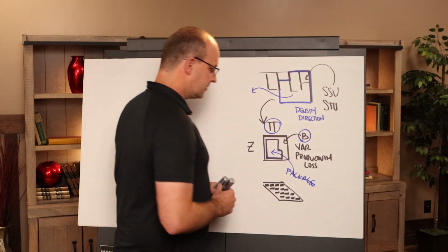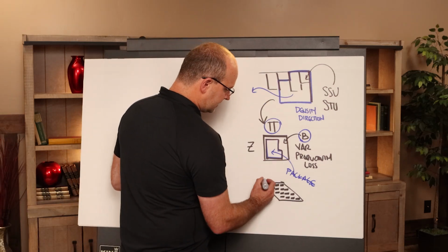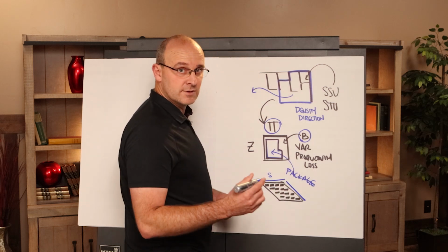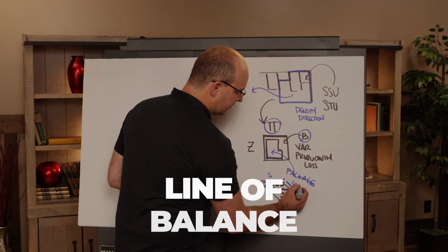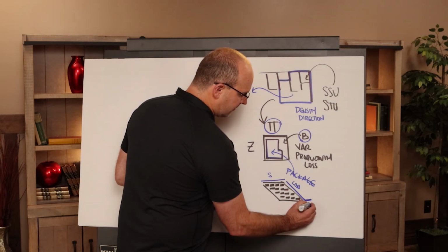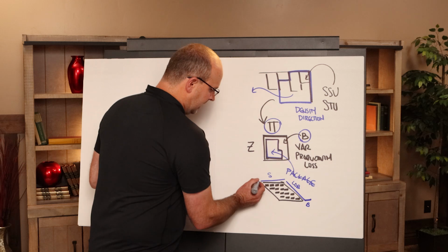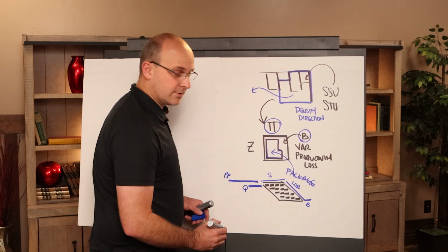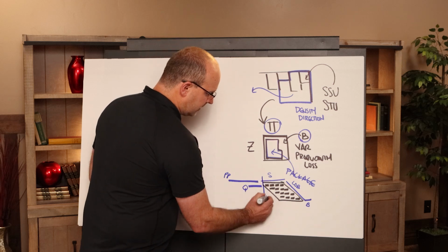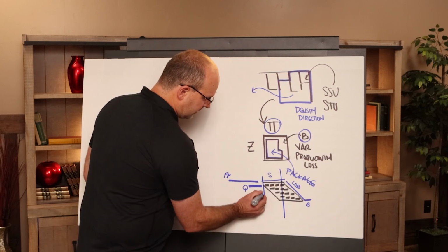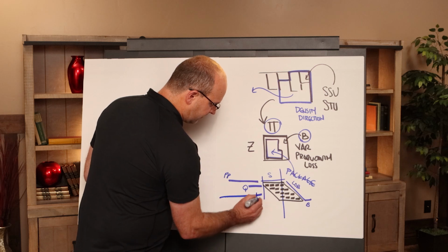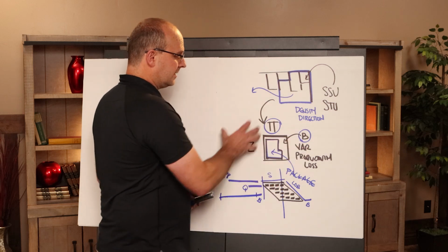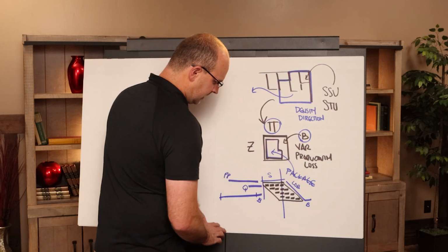Inside the phase, there's a couple of things. You're now looping this into a sequence, which I'll mark with an S. You're identifying the flow from zone to zone to zone in what I call a line of balance. And we always make sure that we have a buffer to absorb the risks of the phase, that we always pull plan 3 months ahead, do quality pre-con planning 3 weeks ahead of the task, look ahead to remove roadblocks, and align our supply chain with a buffer to these tasks in that framework. So this is the framework for everything that we do in construction and in construction scheduling.